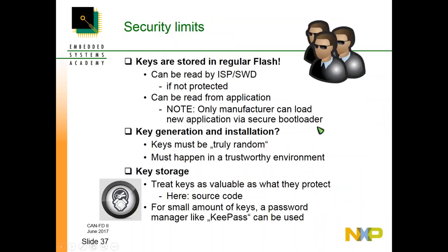Now, where are the security limits? Let's already do a first review. Well, we store the keys in regular flash. So if the in-system programming interfaces or debug interfaces are not closed down, they can be read out, unless flash protection is enabled. The LPC546xx offers flash read protection, so that needs to be enabled if you want to make sure that even locally they cannot be read out. Of course, an application installed will always be able to read it, but well, only the manufacturer can load a new application, so that should not be a problem.